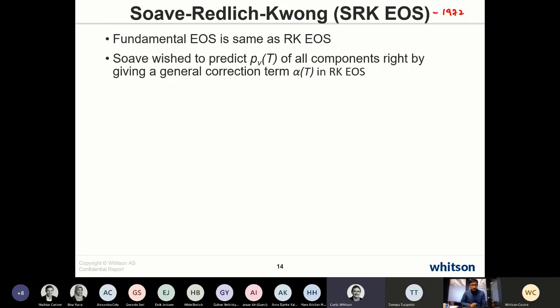Very good, and that's exactly why we discussed all these concepts before, like the K values and the dependency of K values on vapor pressure at low temperature and low pressures. For mixtures, K values are mainly a function of your vapor pressure, the pressure, and the temperature. If you get the vapor pressure right, it means you are getting K values right for the different components at pressures and temperatures on the lower side, for top side processing facility type calculations.